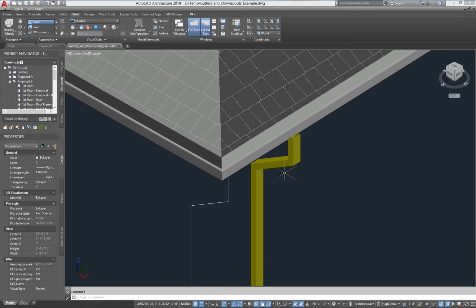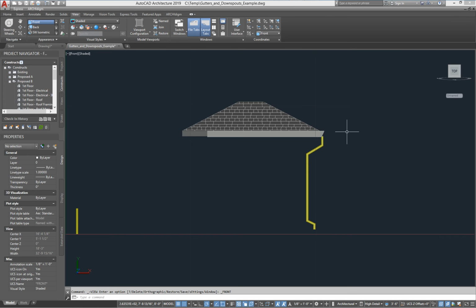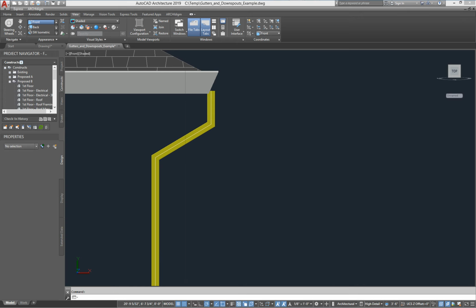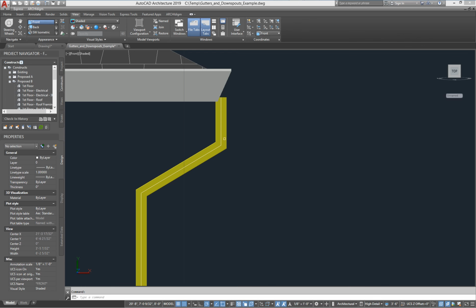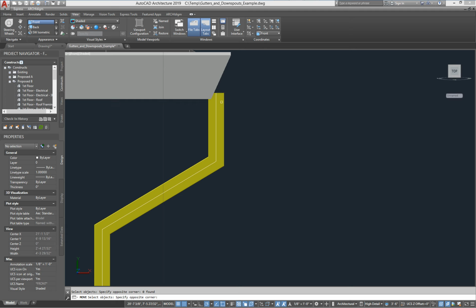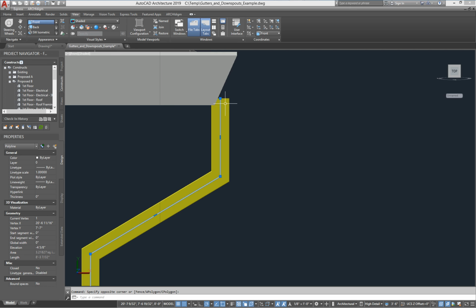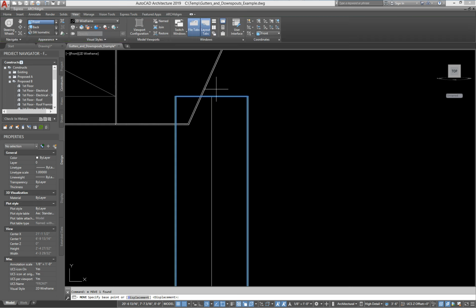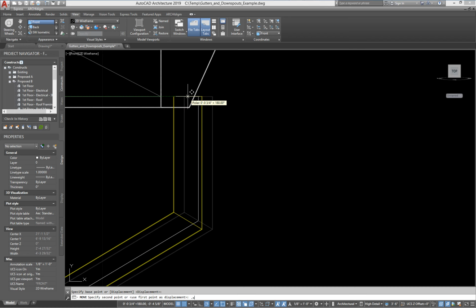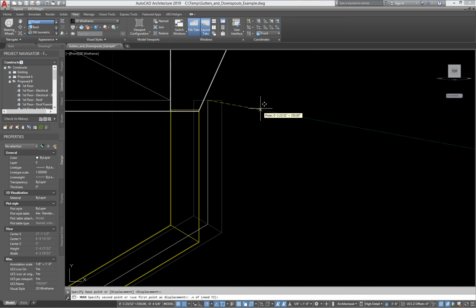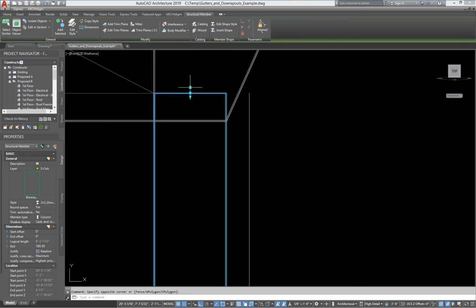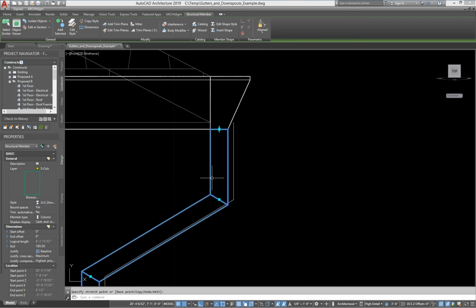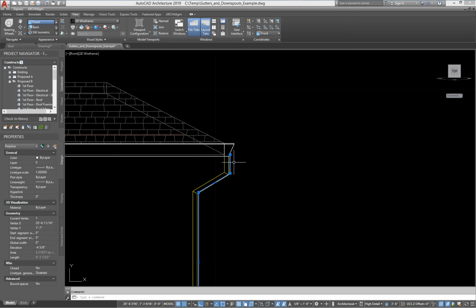Now all I'm going to do is fix that downspout. So I'll go back to a front view. All right. Let's see, we could do a couple of things. The simplest thing is you just take the gutter. Okay, grab it here. All right. Okay, I'm going to get out of a shaded mode here. There we go. And I'm just going to move it from here to a dot X here. And so it lines up like that. So now I can take it and bring it down. Okay, I'm going to get rid of the original line.